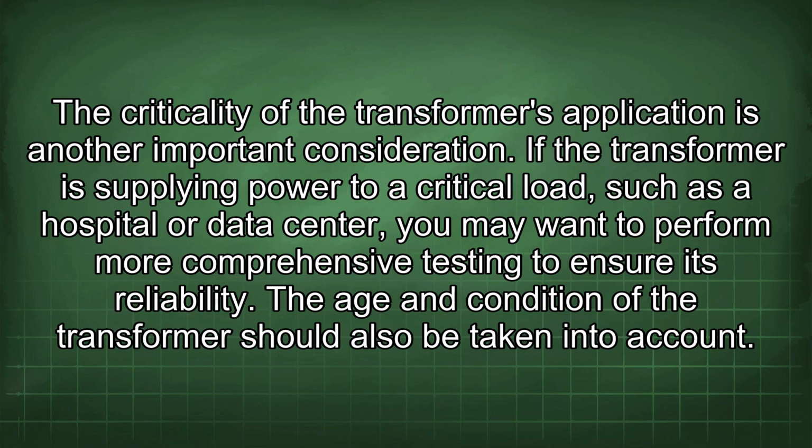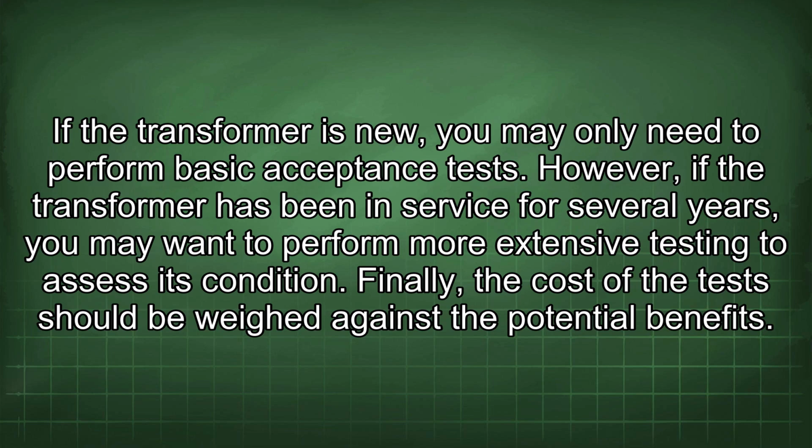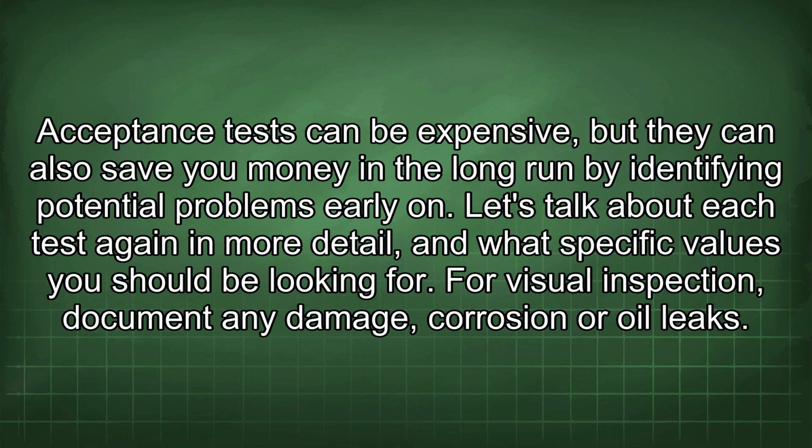The age and condition of the transformer should also be taken into account. If the transformer is new, you may only need to perform basic acceptance tests. However, if the transformer has been in service for several years, you may want to perform more extensive testing to assess its condition. Finally, the cost of the tests should be weighed against the potential benefits. Acceptance tests can be expensive, but they can also save you money in the long run by identifying potential problems early on. Let's talk about each test again in more detail and what specific values you should be looking for.